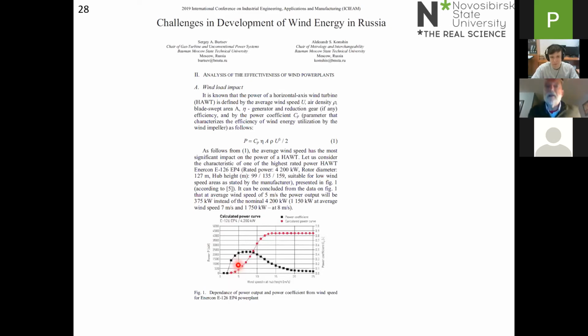Okay. This is not a very fair question for you at the moment, because you probably haven't learned enough about wind turbine performance to analyze this. But the mistake that these authors make is that, by the appropriate international standard, this power curve is determined by averaging the power and the wind speed over a 10-minute period.